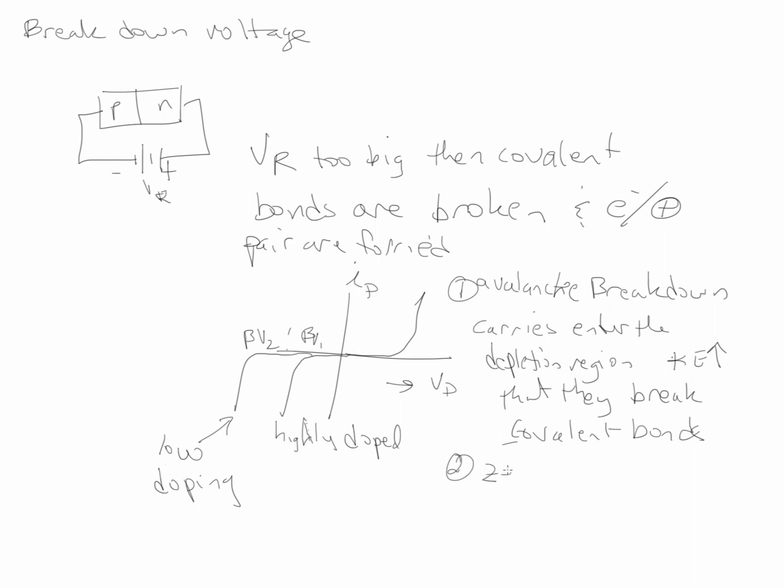And then the other one is called the Zener breakdown, where this consists of carriers tunneling across the junction. So that would be some type of quantum mechanical effect. And this happens at high doping concentrations. And they say in there that the breakdown voltage can be less than 5 volts. And so later on, at the end of the chapter, they talk more about this Zener diode.